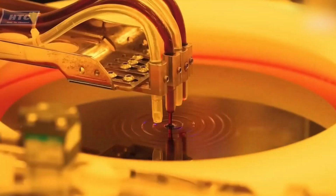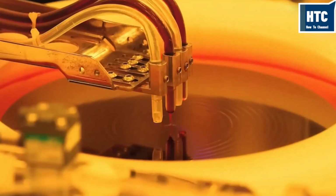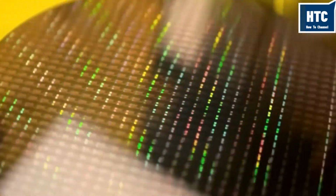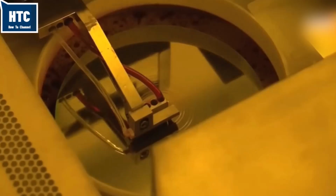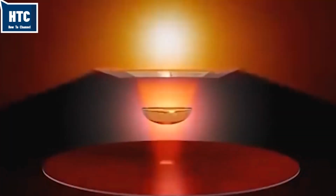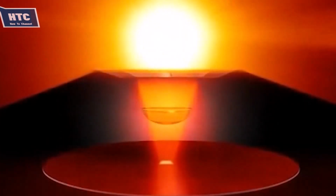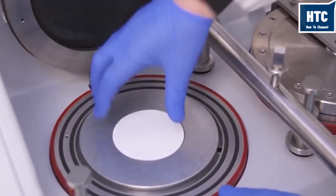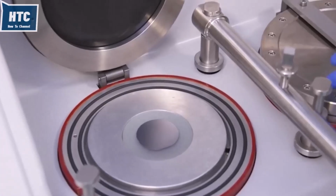Inside the machine, a high-power laser strikes microscopic droplets of molten tin, vaporizing them into plasma. This plasma emits light with a wavelength of exactly 13.5 nanometers. This light is blasted through a reticle, a quartz plate containing the blueprint of the chip's circuitry. The pattern is reflected through a series of mirrors that shrink the image by 4 times, projecting it onto the wafer. Where the EUV light hits the photoresist, the chemical bonds break, changing the solubility.